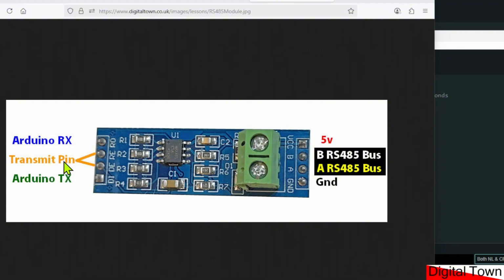Now the transmit pin is a bit like the button on an old-fashioned walkie-talkie. If you had an old-fashioned walkie-talkie, if you release the button, it will receive communication. If you press the button, that is when you speak. Now that's exactly what's going to happen with this module. So whenever we want to send something, we send the transmit pin high, but as soon as we've finished transmitting, we set the pin low so that we can then receive any communications on the bus wires.